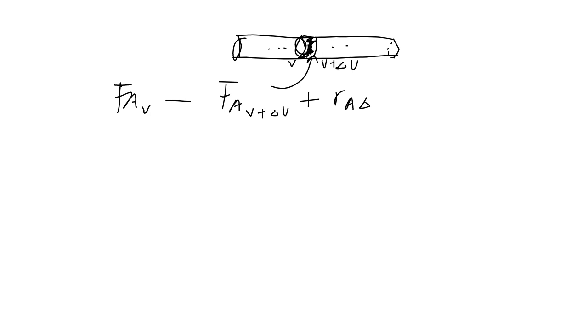And if I do my energy balance over that slice. So let's just first do the mole balance. Let's say I've got FA at the inlet of that slice, where V is equal to V, minus FA when it comes out at V plus del V. You should all remember this from your, well, maybe not remember it, that's a tall order. And then I've got this conversion in that slice, and that is equal to plus the rate in that slice times the delta V in that slice. Must be equal to 0.